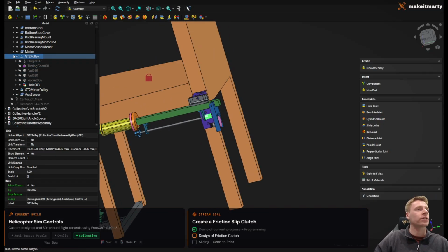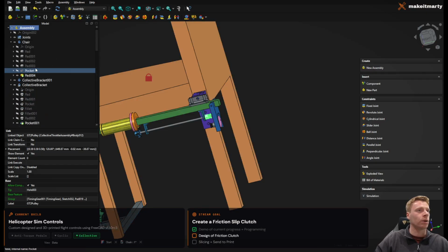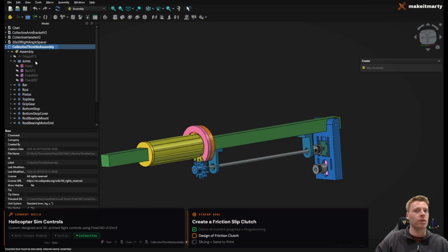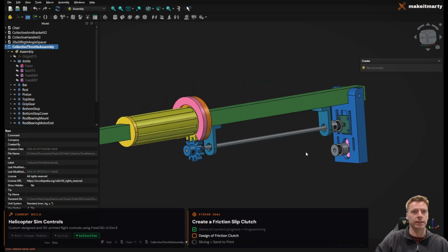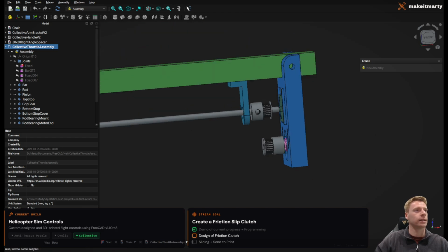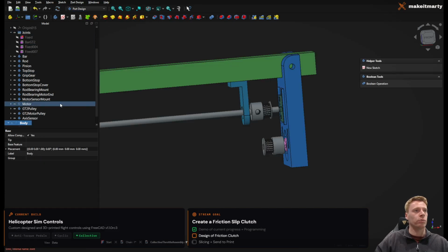So what we can do, let's make a new part. We have a lot of stuff open, so what I might just do, let's pop into this one. Here we go. So we've just isolated it essentially. This is nicer. We're going to go down to the part design workbench, and we'll create a new body here.